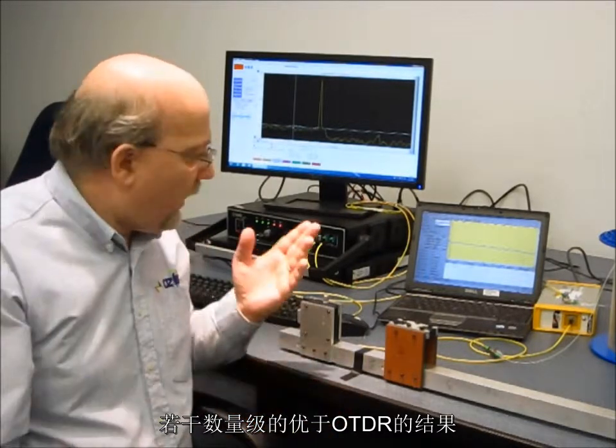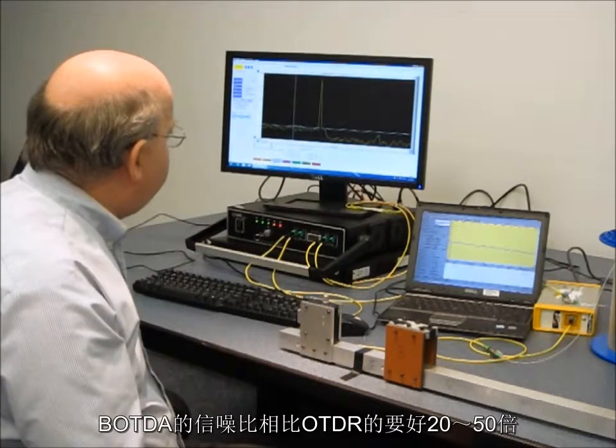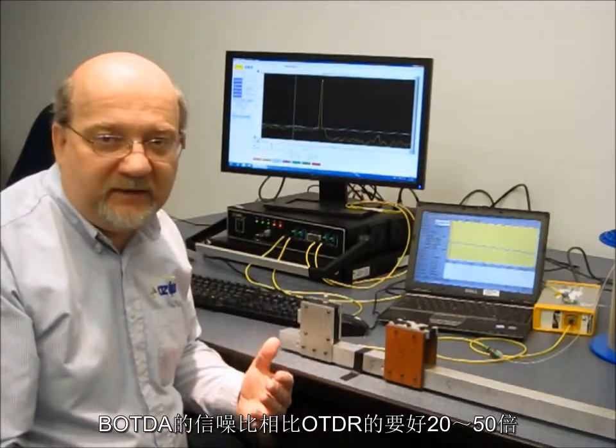So this clearly shows how the Brillouin sensor is capable of measuring changes of strain on a fiber on orders of magnitude greater than what an OTDR can detect. Okay, roughly speaking here, we have a signal-to-noise ratio of anywhere between 20 to 50 to 1 that it can measure a signal on a BOTDA while being undetectable with an OTDR.